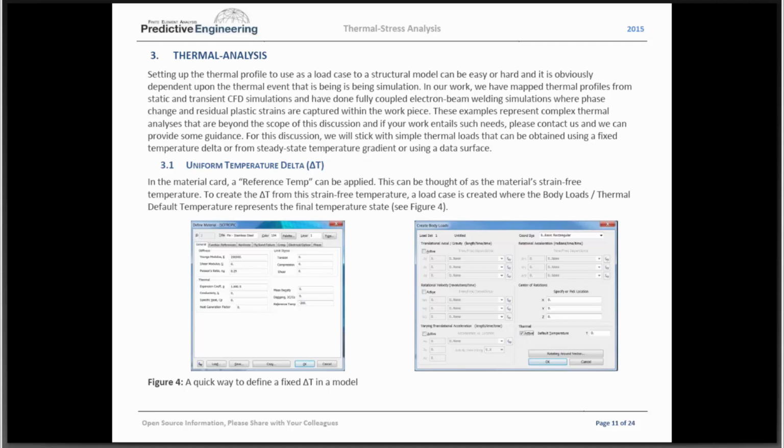And then as it starts to cool down, metals, of course, the elastic modulus will change as it cools. When it's red hot, the elastic modulus is quite low. That's what blacksmiths like. They can heat it up to red hot and pound on it. You get stress-free plastic deformation. So in welding analysis, you pretty much say that your stress-free temperature is 1,000 F or more, and you cool it to room temperature, and you get these huge stresses that come up.